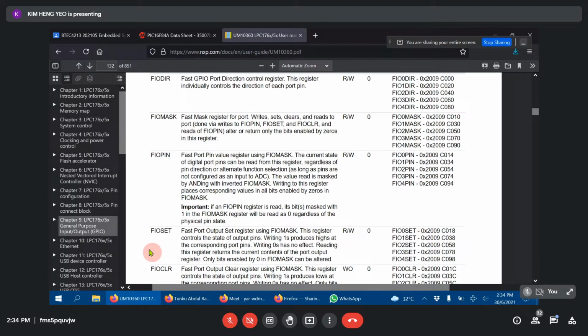Race condition. You remember in computer architecture, race conditions can happen. If you are doing something which requires a few clock cycles, you may be interrupted in the middle of doing it, because the processor can receive interrupt requests. So let's say the processor is doing a read modify write operation.